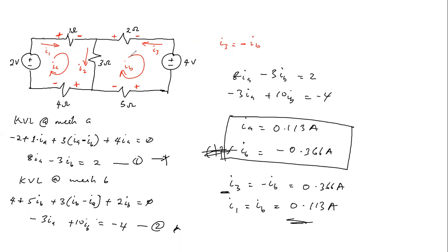Okay, just like in the nodal analysis where we had a special case where a voltage source is connected between 2 unknown voltages, or better still, between 2 independent nodes, which led to the supernode concept, the same thing applies in the mesh analysis, where we have the super mesh concept, where a current source is connected between two meshes.